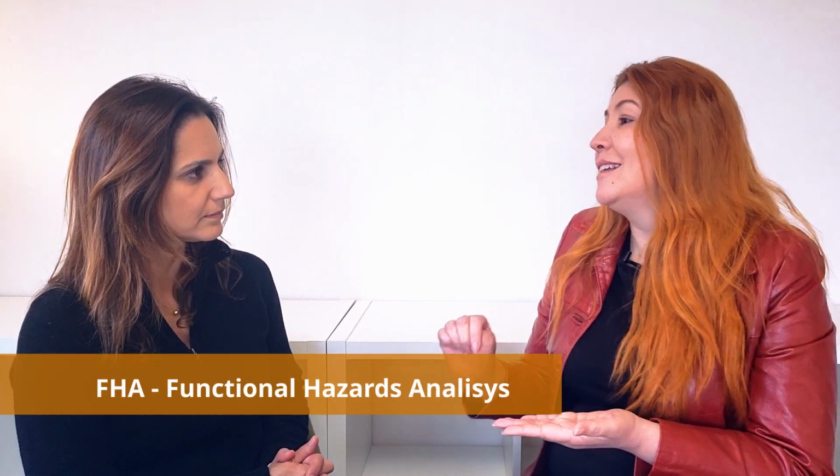And how does it start? This starts with an analysis that we call functional hazard analysis. When you are talking about an aircraft, we usually start with an aircraft level analysis, but this tool can be used for system level, subsystem level, so we can go down to any level. But if you start in the beginning of the development phase, we define all the functions of the aircraft and identify all the failure conditions and malfunctions, and classify those failures and malfunctions according to the severity of the effects of their occurrence. And this evaluation is done at the level of the aircraft, the crew impact, or the passengers impact. Okay. And what about the preliminary safety assessment?